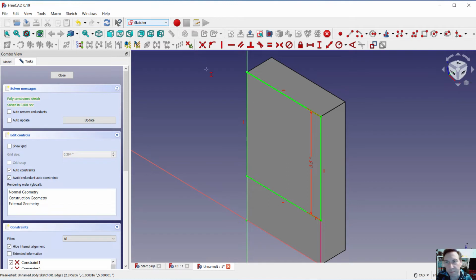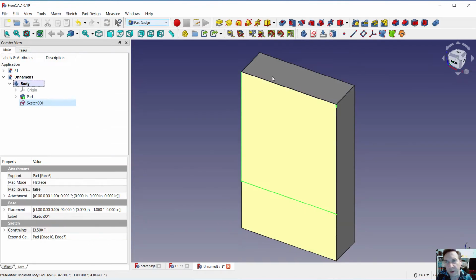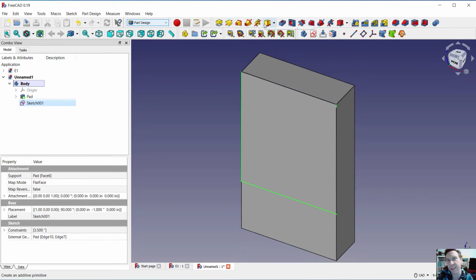Now we're going to cut that. So we're going to find the solid tools here. Oh, actually, first we have to hit close. My apologies there. Hit close. All right, and now notice the yellow tools here. These are for adding material. The blue and red are for removing material. Okay, so right here we have create a pocket. Go ahead and select that.